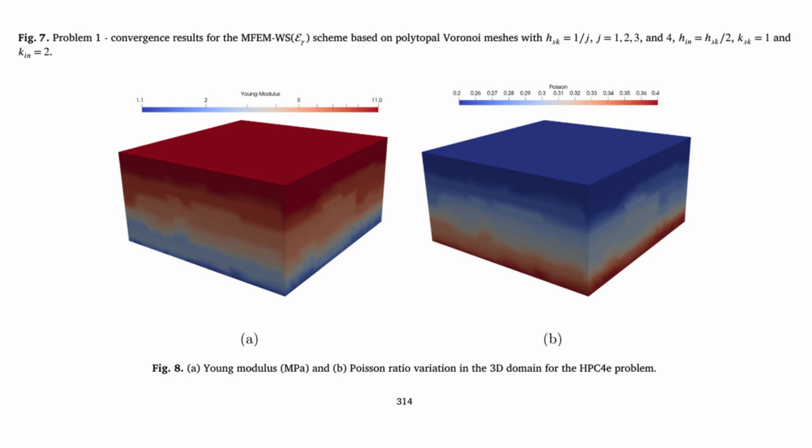Okay, this is the really clever part, isn't it? If you're only solving globally for stuff happening on the boundaries and the overall block movements, aren't you just shifting the computational work from the inside to the surfaces? You are shifting it, but you're shifting it onto a much smaller set of unknowns. The skeleton, the network of faces, has far fewer degrees of freedom than the entire volume. You concentrate the main global computational effort there. And the fine details, the stress and displacement inside the blocks?